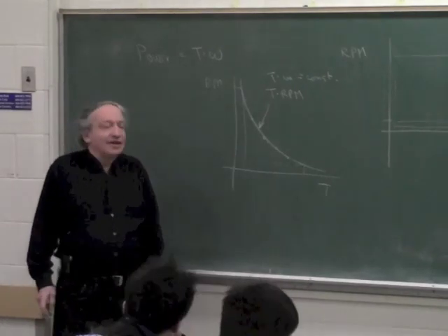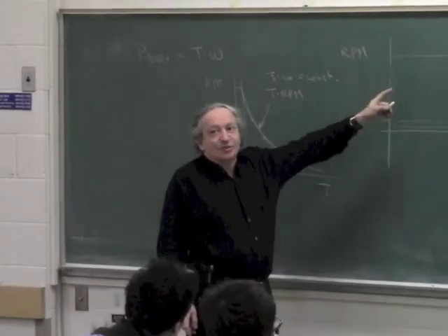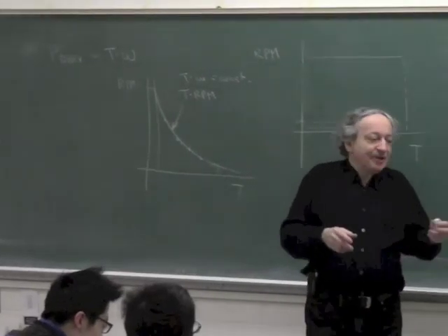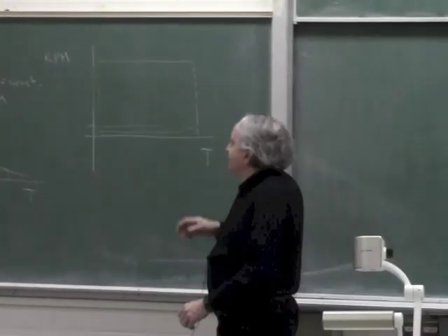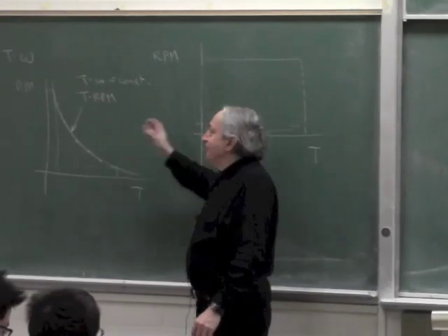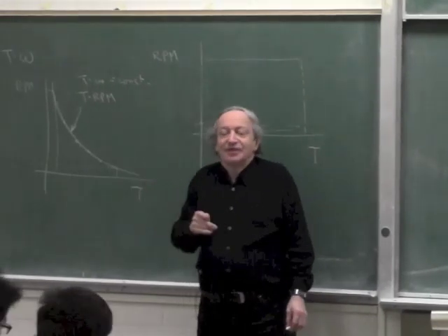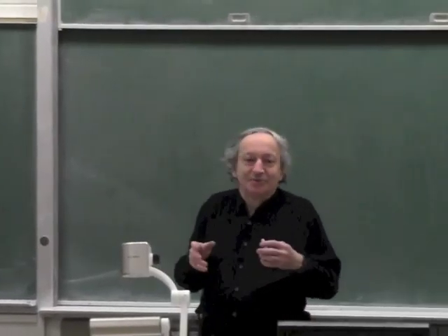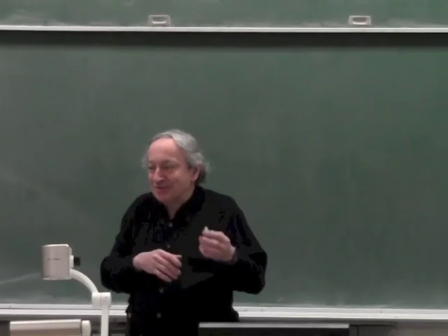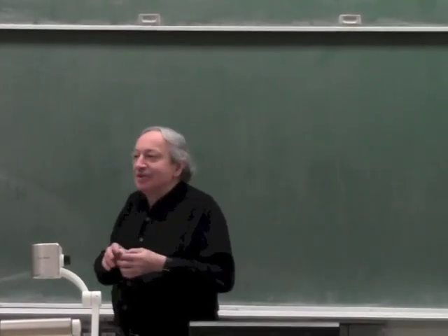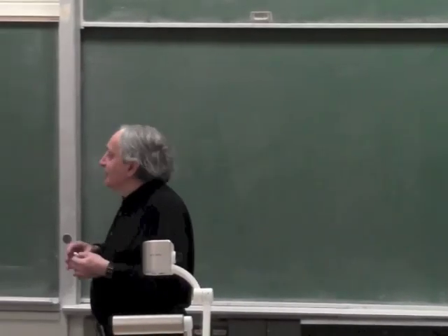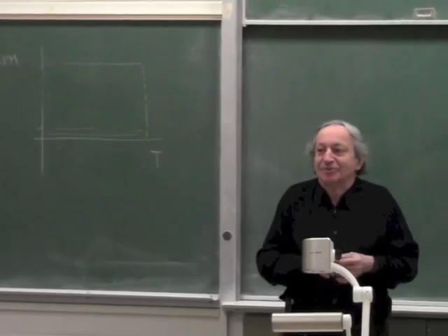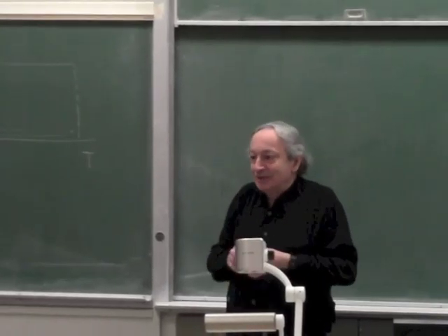If you connect it in parallel, it has this curve, or almost this curve. So basically, by taking the same motor, and depending on how you connect it, you can get this curve or any curve in between, actually. And that was very, very important in the days where there was no electronics, where you could easily do PWM and switch and control things, which today you can. But even today, with electronics and PWM and everything, this is very, very desirable, because the motor already comes like this. You don't have to waste money or power to make it look like this.